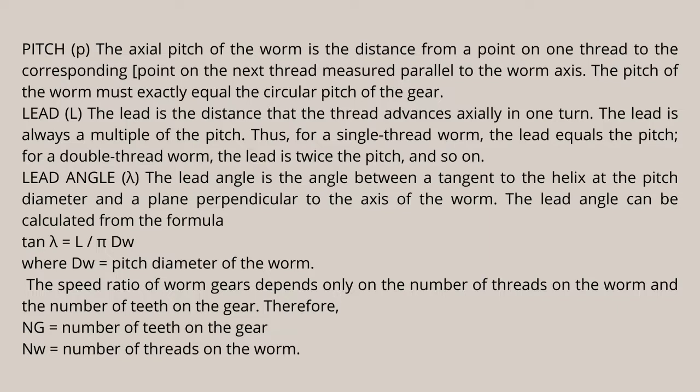The lead angle is the angle between a tangent to the helix at the pitch diameter and a plane perpendicular to the axis of the worm. The lead angle can be calculated from the formula where dW is equal to the pitch diameter of the worm.